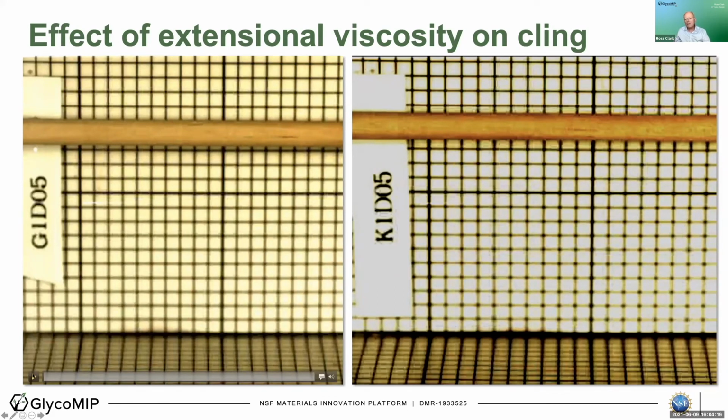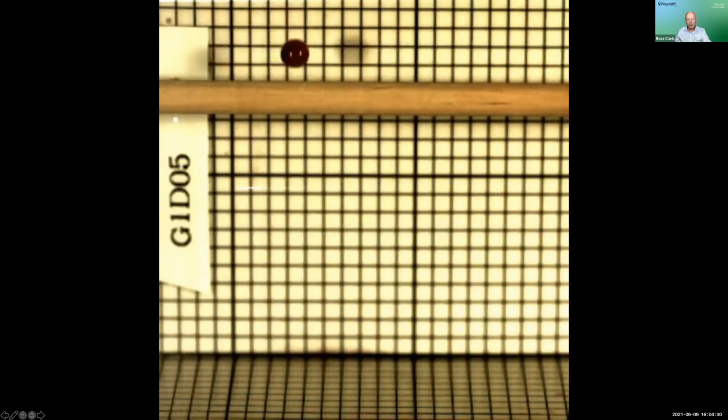The first one has a very high Trouton ratio. That is, it has a lot of extensional viscosity compared to the shear viscosity. And let's watch the little dance that it does as it falls. So this liquid, now you can really see what extensional viscosity is. And if you watch in this area down here, you're going to see a fascinating behavior because this very elastic fluid is going to create satellite drops. And just watch right here as those drops, it gets thinner and thinner, and they just slam back together into one another, which they're about to do right now.